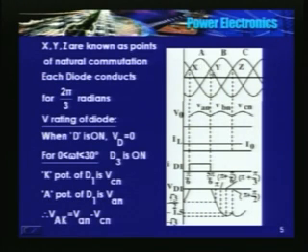Similarly at Y plus, phase B becomes more positive than phase A, and similarly at Z, phase C becomes more positive than phase B. With the common cathode configuration, the diode whose anode potential is highest will start conducting.